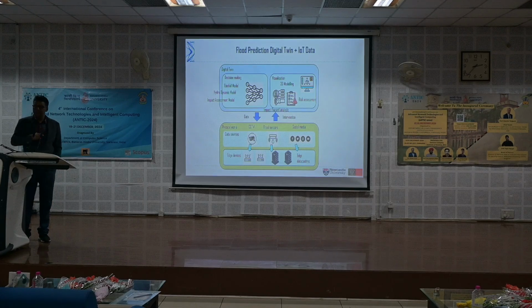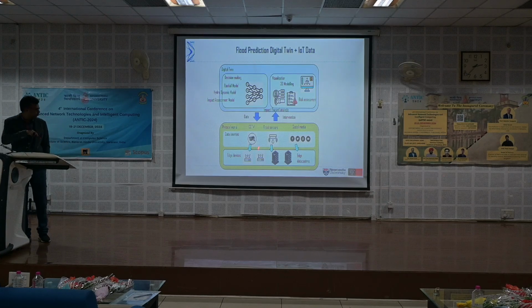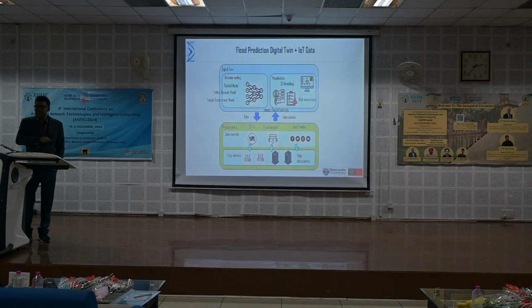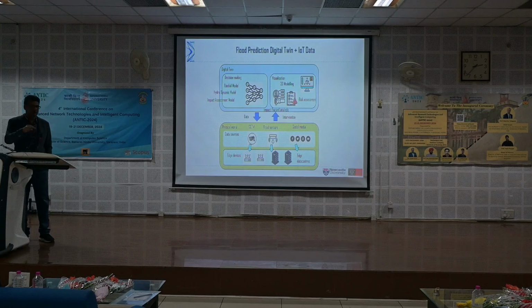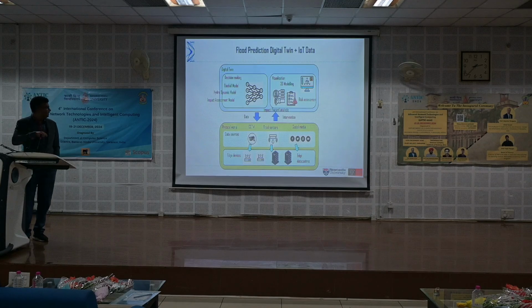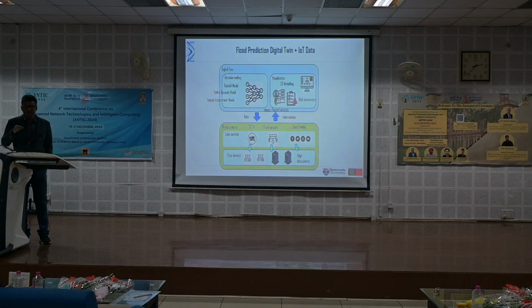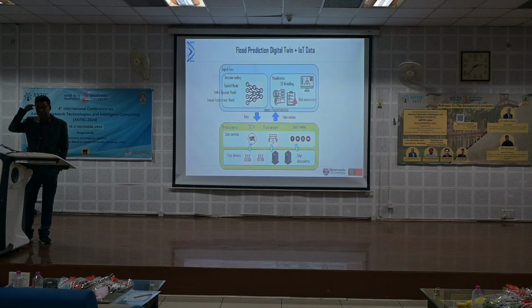Most of their models will be based on complex physics simulations, which is not good for real-time data. So maybe you need to work with them, convert those models to AI models, surrogate models that can take the real-time data. So there's a lot of research to be done on surrogate modeling of the traditional models, because traditional rainfall models are just differential equations. They don't take real-time data from the sensors. So you need to work with them to convert those models into AI models. Again, some research is required on that, and each of the models is different for different cities.